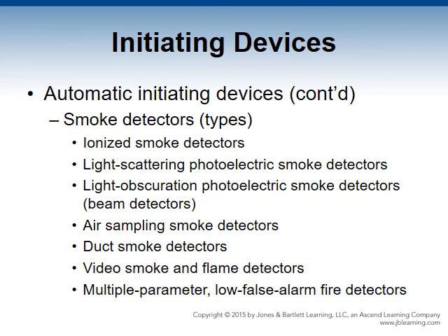Different levels of alarm communicate how much smoke is present. A cloud chamber type detection creates an environment within the detector chamber where condensation forms on smoke particles, causing them to increase and eventually initiate an alarm when they exceed a predetermined size.